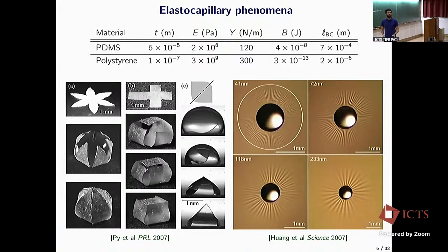interfaces. So if we take, as a reference, the air-liquid interface, we know that the surface tension of the air-liquid interface is of the order of 0.1 Newton per meter. Okay? So if you compare, you see that this value is much lower than the stretching modulus. So it means that the air-water interface will not be able to stretch these sheets.